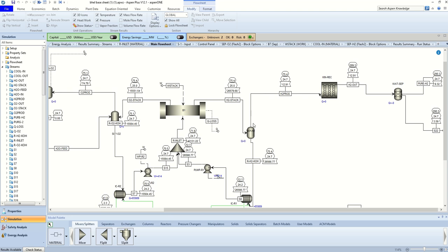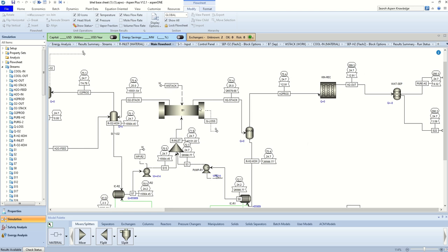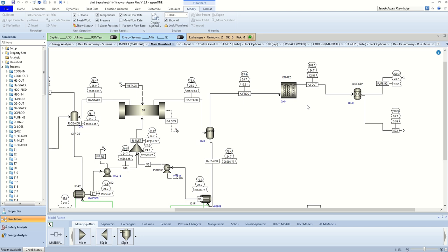So after the flash separation we get a stream which contains very much less amount of water than the previous one, but now there is some oxygen impurity that is present in there. So this stack has been built for 25 bar pressure and 75 degrees Celsius, the alkaline one. So for the oxygen impurity we have provided a kinetic reactor which reacts with the excess hydrogen, and this oxygen is well below the lower explosion limit, as we can see in the results.